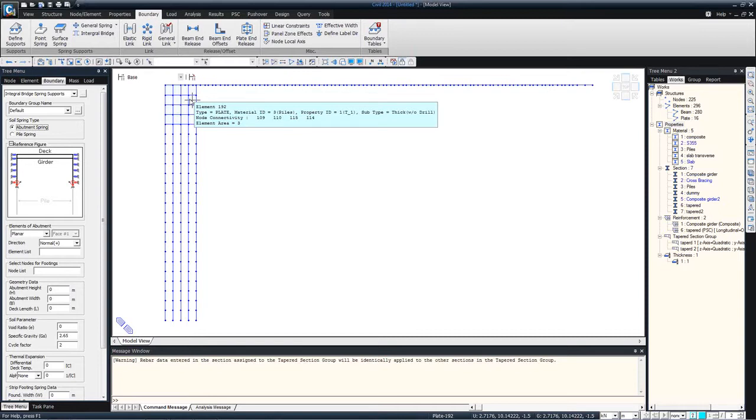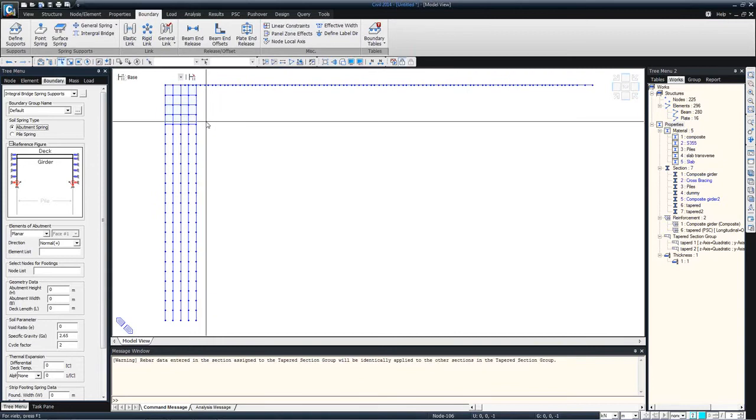So there is a constant separation, or you can say the backfill constantly undergoes a fatigue, like a cycle of expansion and contraction in the deck. So this effect should be considered in the soil structure interaction, and the term for this is strain ratcheting, and you can consider this in the software just by simply selecting a few abutment elements.